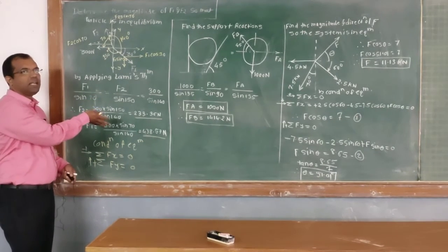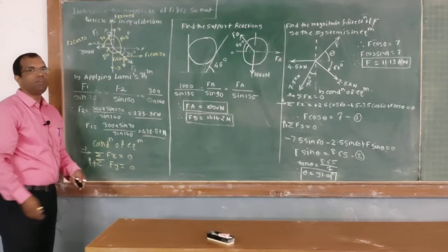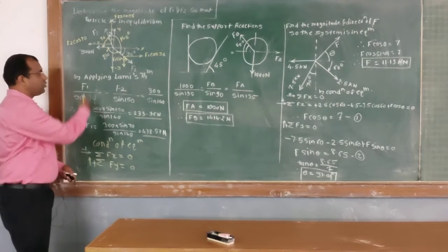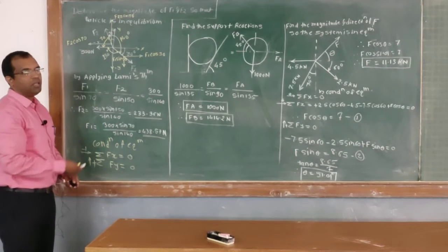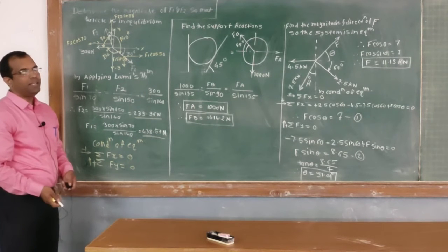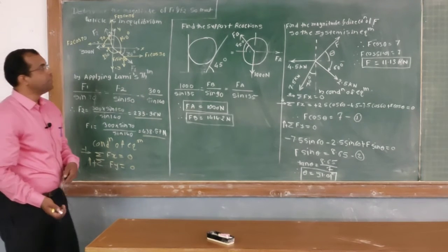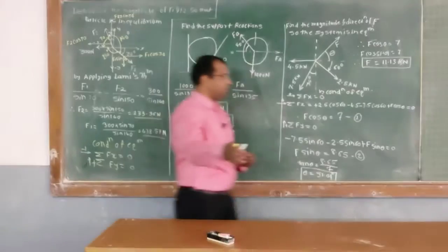My suggestion is that when three concurrent forces are given, you should solve the problem by using Lami's theorem. It will save your time and definitely within 2 steps you will get your answer. Okay, so let's come towards the next problem.